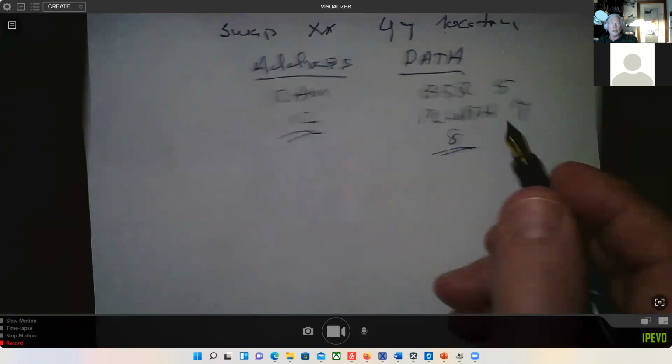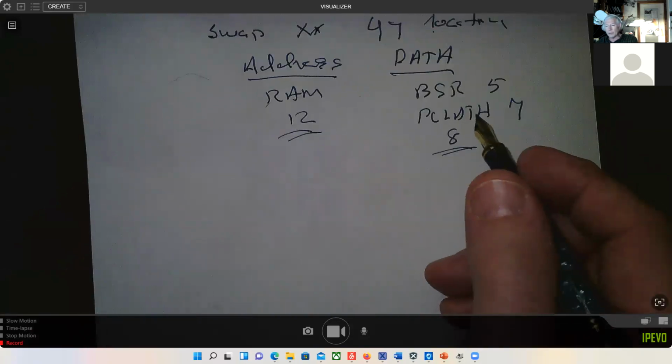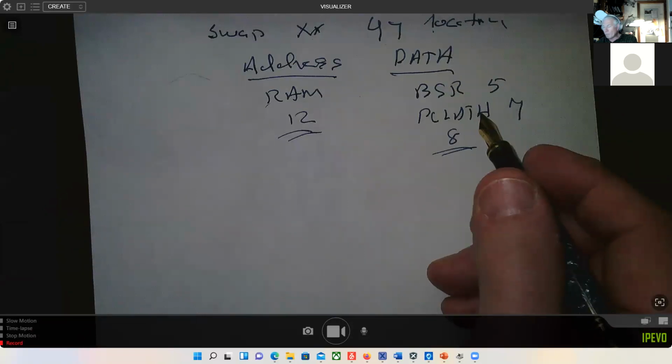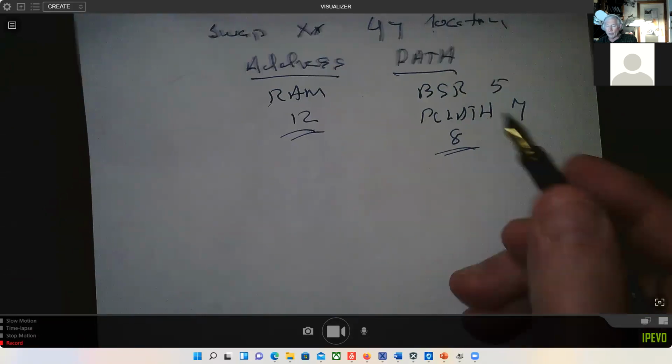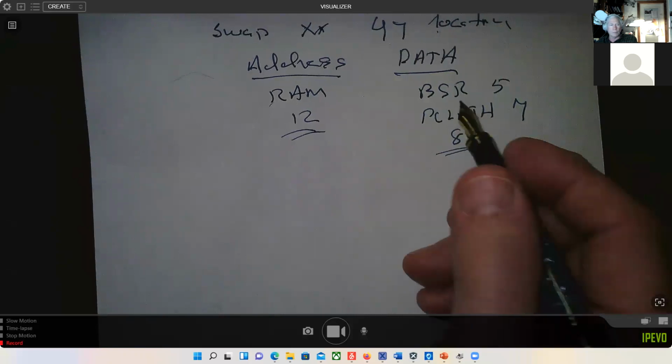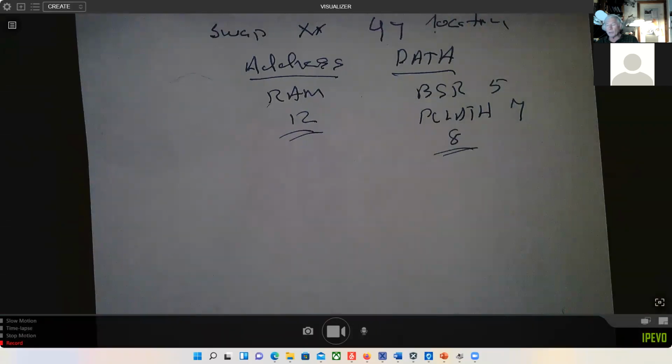A lot of the registers that control the various modules may be missing a bit here or there, but you can write an 8-bit value. The bits that aren't implemented, you just write zeros, and you typically read zeros. So you just kind of ignore those bits.